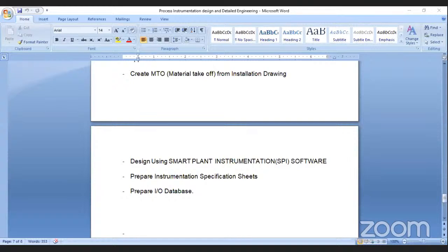Especially in oil and gas fields, this is very important. Based on the IO modules, we also have power and heat rise calculations. Here also we are using software to work out how much power is required for your cabinet. That is very important. That is based on what? Based on the number of IOs and the number of modules in the cabinet. So that is an enclosure rating.